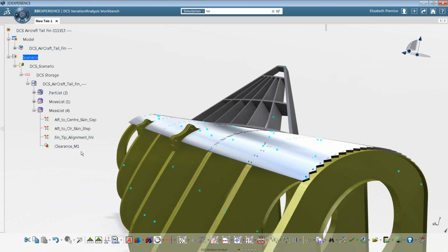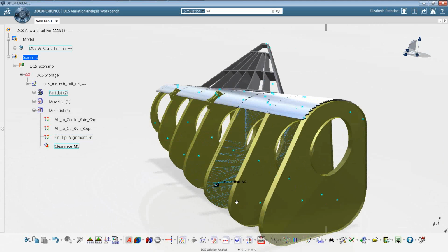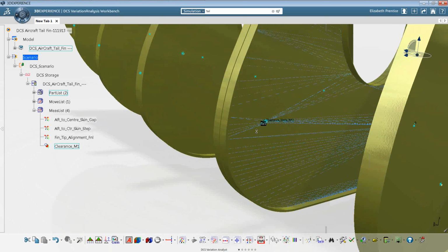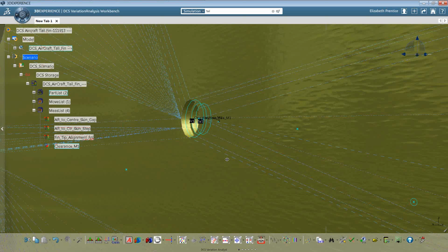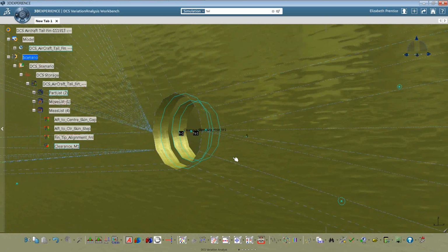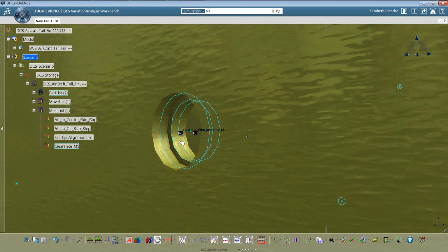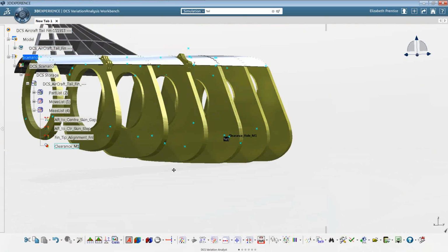And the final measurement we're going to look at, these are just, for example, is the clearance between two holes. And if I zoom in here, we'll build it in a bit, but you'll be able to see there's two frames that are coming together, and each has a separate hole on it. So let me zoom in here. So you can see one frame has a slightly smaller hole than the other. And what we're going to be measuring is figuring out what is the largest size pin that can fit through both of these holes.